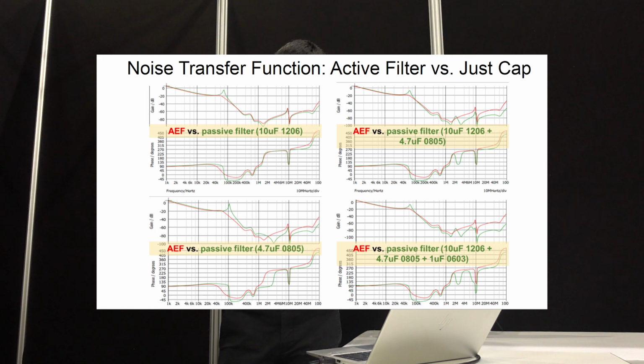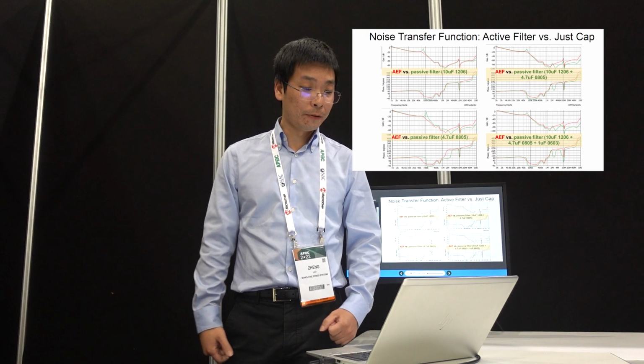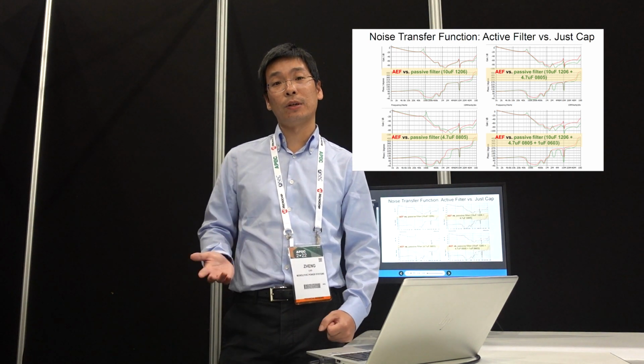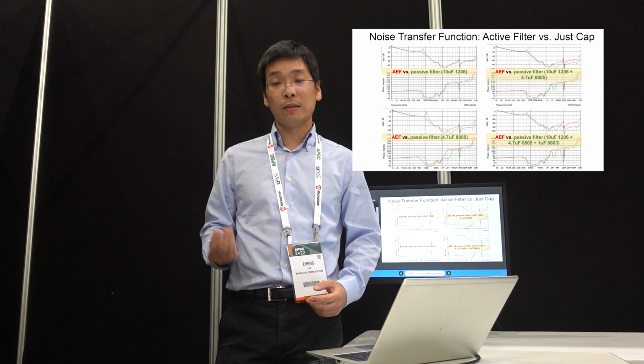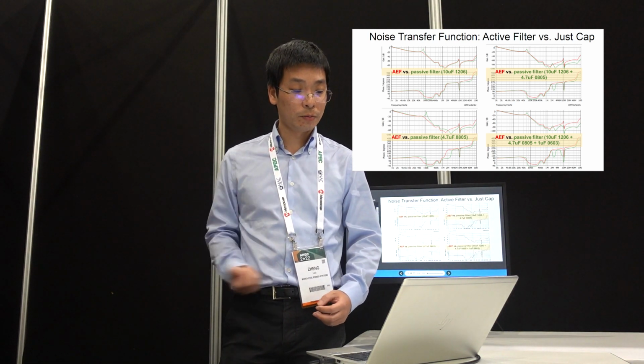Better is good, but what is good for your case? It really depends. For example, if your switcher is switching at 2 MHz, which is very common in our module space, the gain that we have below 2 MHz actually doesn't matter, right? Because you don't have noise there, and it's more important that you have the gain to suppress the noise after 2 MHz.